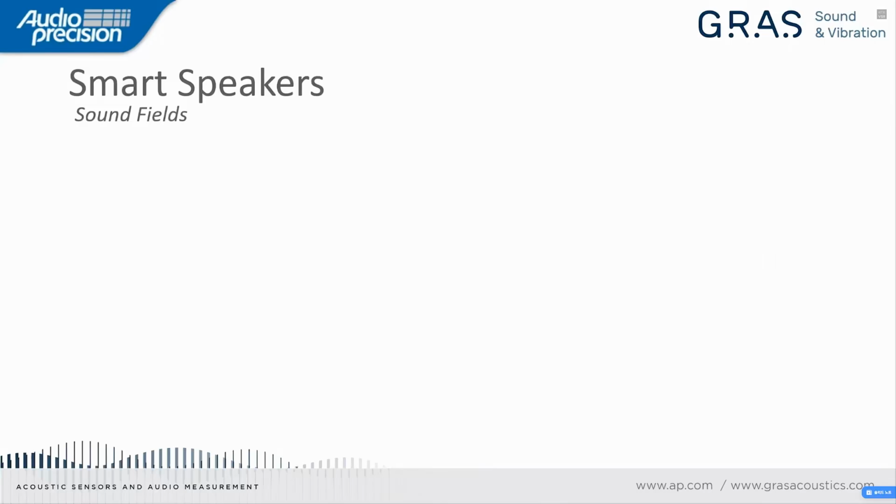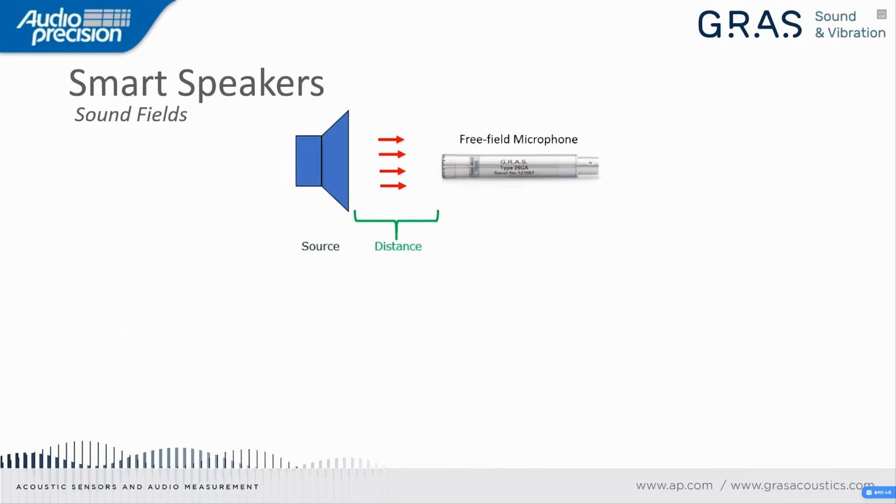When we are testing smart speakers, it is also important that we look at the sound fields for selecting the right microphone and measuring the right response from the speaker under test. In most cases, when we are measuring a loudspeaker, we have the speaker, the source itself, and at a certain distance we place a microphone.